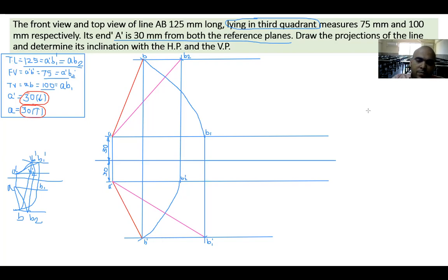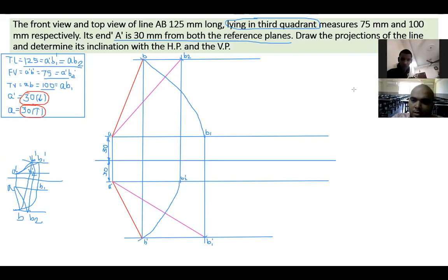Yes, Prakriti. प्रकृति बोलो. सर B1 से B1 डैश कैसे बनाना है? हाँ. So from B1 you have to make simply a straight line. Okay. And then you take in your rounder 125. And from A dash you make a cut to this line. Wherever you will get a cut, that is your B1 dash. Okay, sir. There you make a locus line. And then the further process. Yeah. Lower your hand, Prakriti.